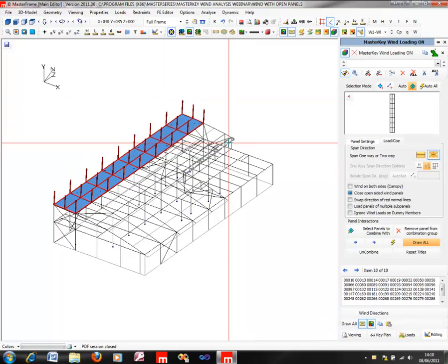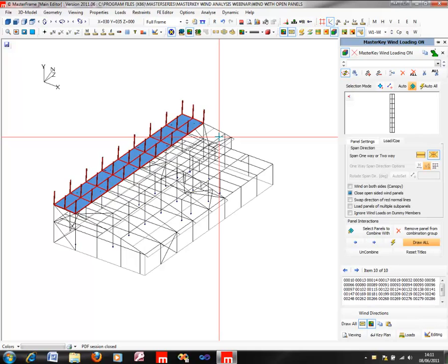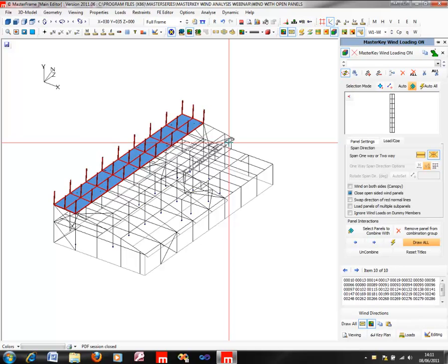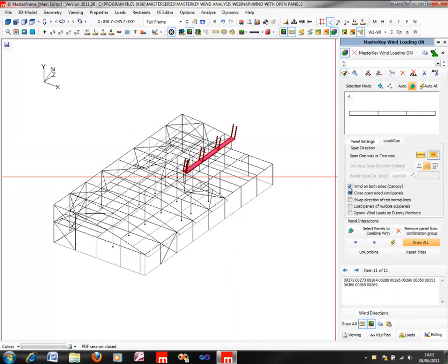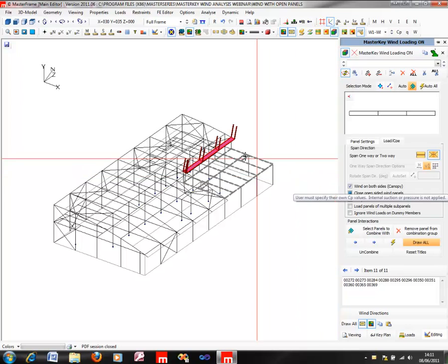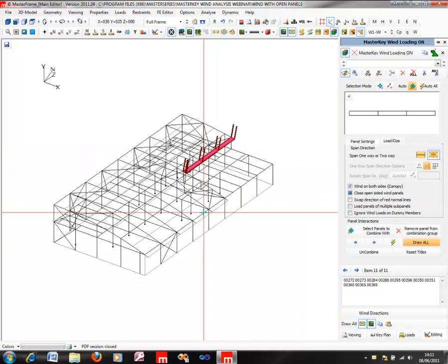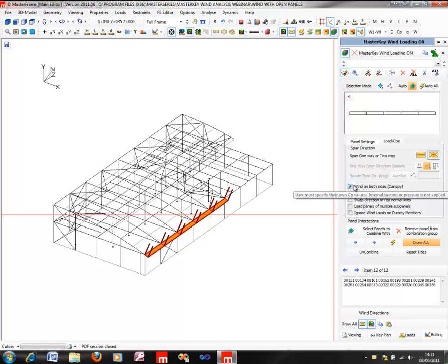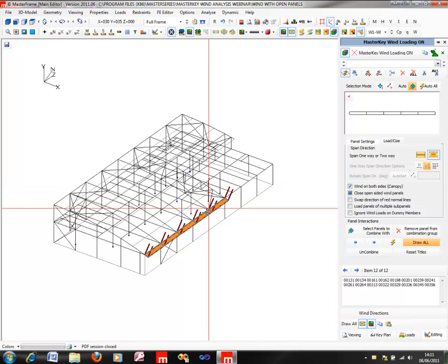we can see that the main reason for that is because we've got this projecting as a canopy, and the program does identify canopy surfaces as separate from the main surfaces, which have wind loading on the outside and the other side is internal. So when I click on this, it does automatically check the canopy box to say that it is a canopy surface, so that will split that up. And the same thing goes for this one down here. You might have expected it to be part of this surface, but it's kept separate with the canopy option checked to set it as a canopy as such.